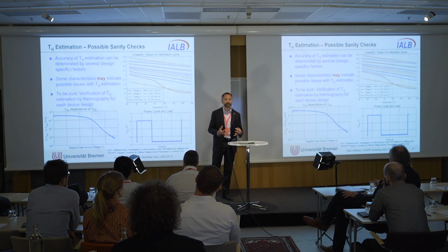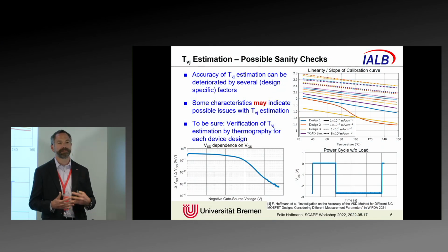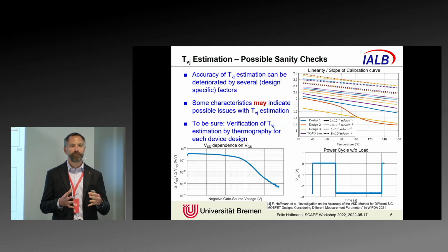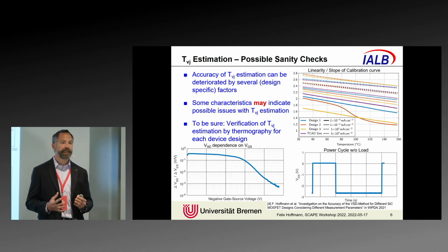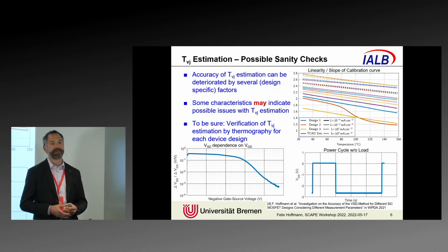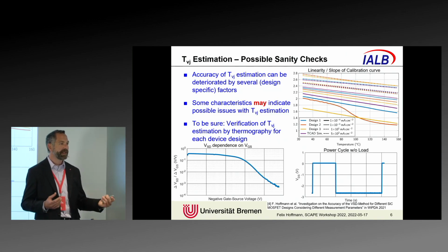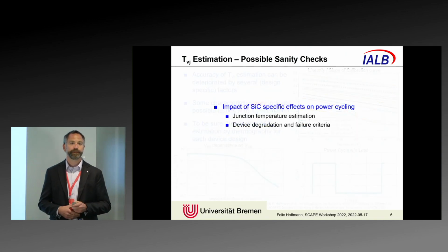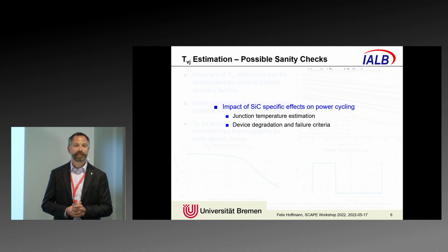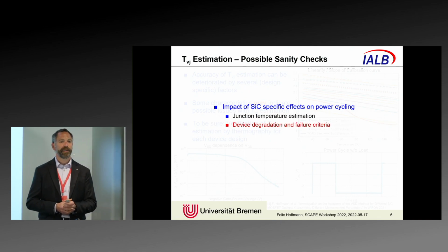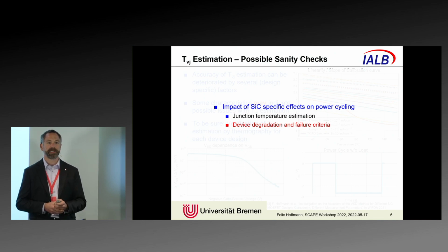To be sure, you really need to verify this temperature estimation, for instance, by thermography. This needs to be performed for each device design if you really want to make sure that your reading is accurate. Now let's talk about the second chapter, the impact of device degradation and failure criteria.